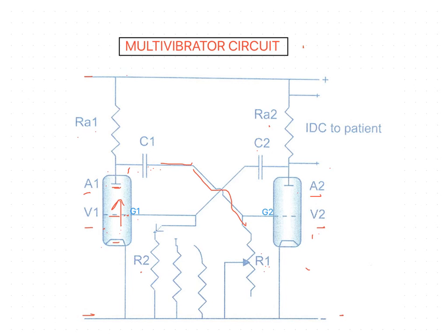Such small variations normally occur in this kind of multi-vibrator circuit, because it is a very sensitive type of circuit. A rise or fall in the intensity of the current flowing through either of the valves, caused by any disturbance, initiates the action of the circuit. Only if some interference is caused does the multi-vibrator circuit begin to act. Otherwise, it will have the normal flow of current.